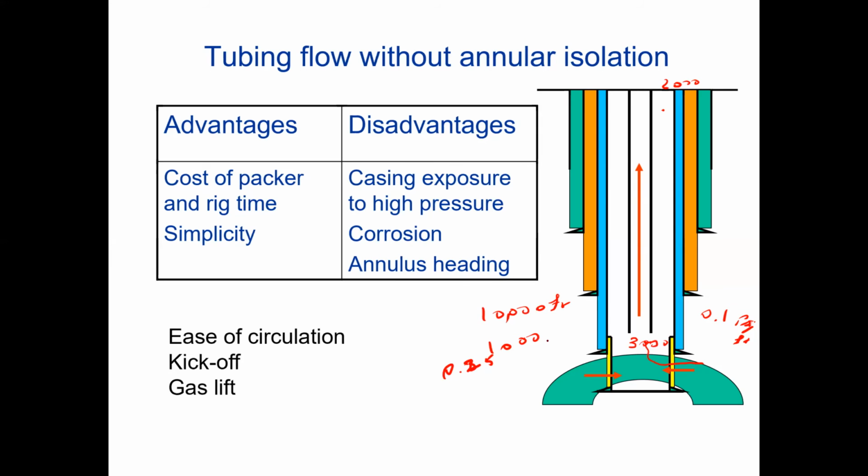So this is 2.5, and then 3,000, over 10,000 feet depth becomes 2,500 hydrostatic head. And we have also frictional pressure drop, and the pressure at the surface could be 500. So you see that in the annulus the pressure would be very high, and that is dangerous.